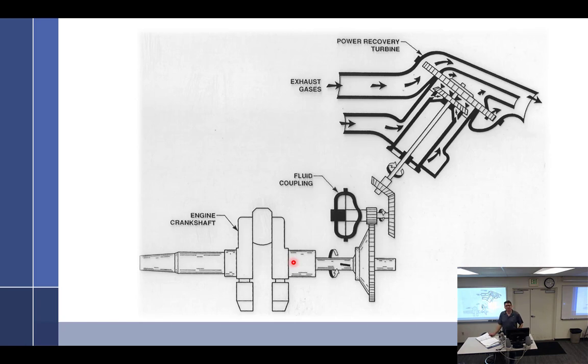Normal sea level pressure is at a certain level, and we're no longer at sea level pressure when pressure drops. What's the main limiting factor in increasing manifold pressure? Why can't we just keep on going? Heat, and that leads to detonation. Bad things.